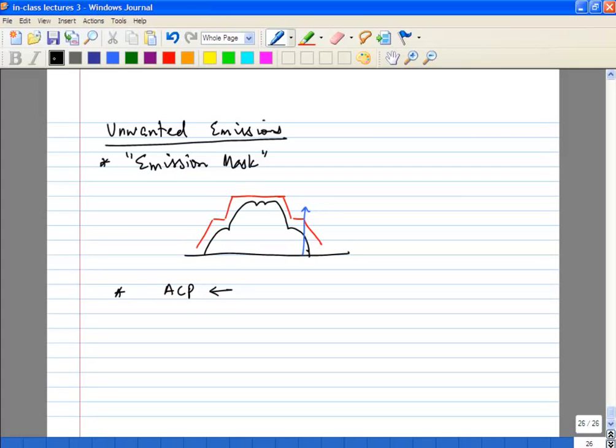Different standards will have different requirements. CDMA calls it ACPR, WCDMA calls it ACLR, or adjacent channel leakage power ratio. GSM calls it ORFS, or output radio frequency spectrum. They all mean the same thing; they are basically defining an emission mask. Obviously, spurs, whether they are produced by the mixers, PLLs, whatever, doesn't matter. We should get rid of them.